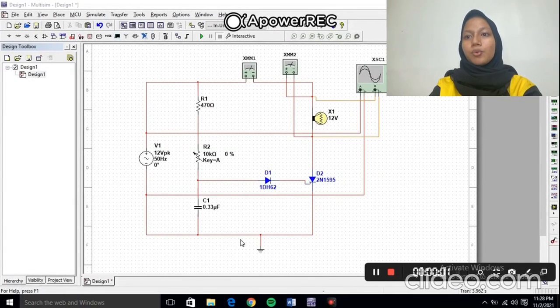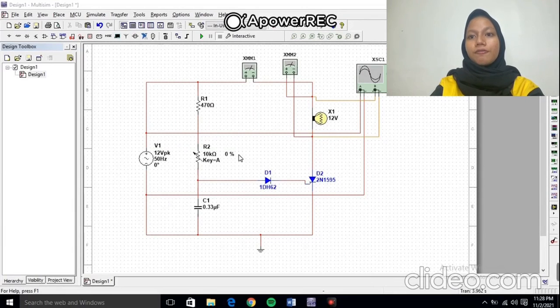Okay, first, we need to construct a simulation using Multisim, featuring figure 4.3. So first, we need to put the V source, which is the V peak, and then we set it to 12 V peak and 500 Hertz at 0 degree.